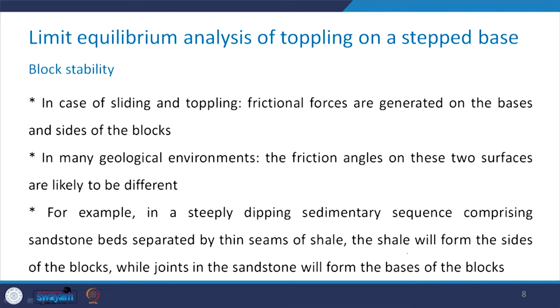For example, if you take the steeply dipping sedimentary sequence which is comprising of sandstone beds and separated by thin seams of shale, in this case what will happen is that the shale will form the sides of the blocks, while the joints in the sandstone will form the bases of the blocks.